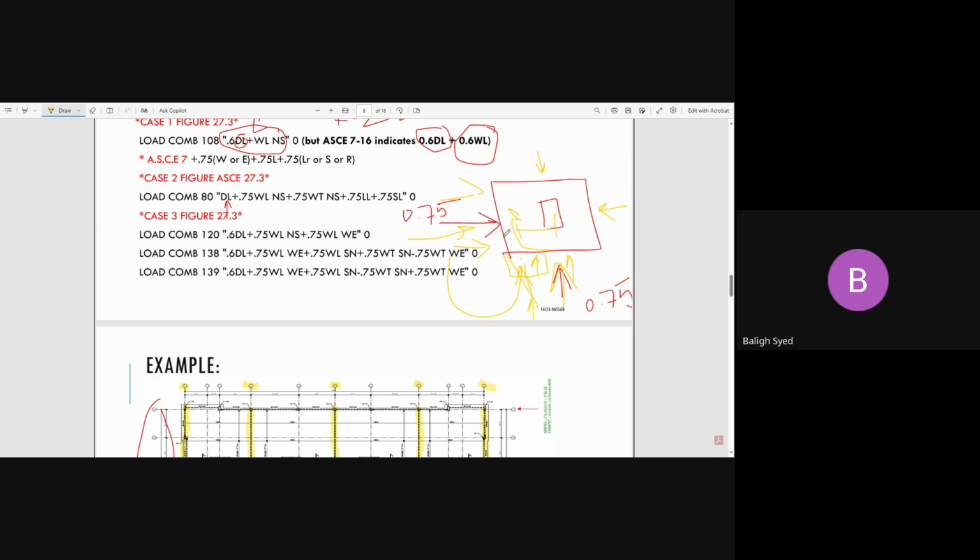So it can hit from here, or it can come and hit from here, because it's not like seismic. Wind is completely different. Wind is completely unpredictable. That's why the code is so stringent. We have seen a significant difference between wind tunnel pressures, when we do power plants and request wind tunnel pressures, and the pressures developed by ASCE 7 for the same height of building.